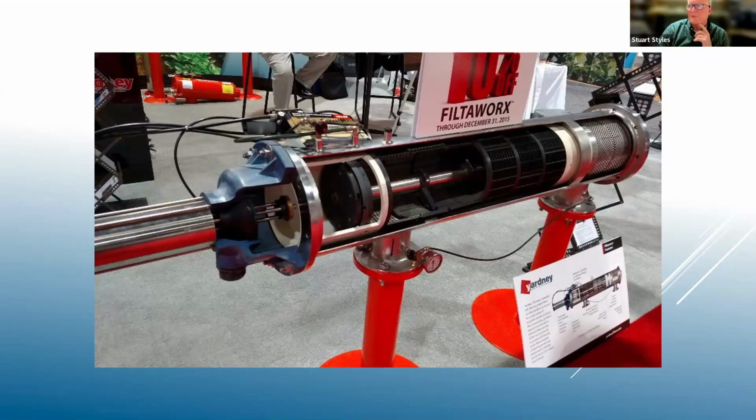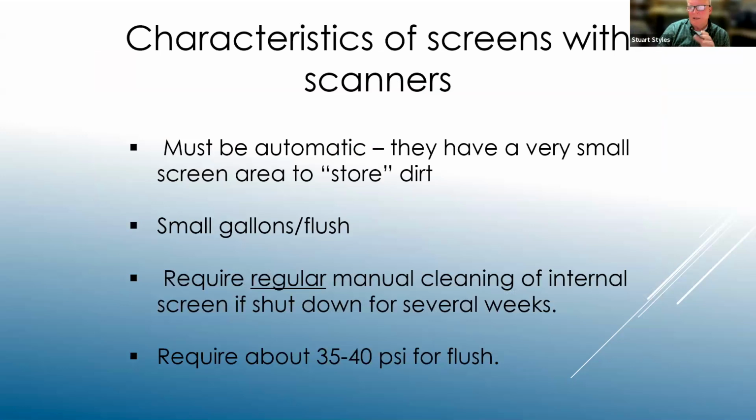So it's a very effective way to set up filtration out there. I had some bullet points on this, but I've kind of covered them already. The big thing that it does is it doesn't require as much of a backflush water cycle as the sand media tank. So that's one of the big selling points. But it does require a really high pressure for it to work. If it has low pressure, it just won't work.